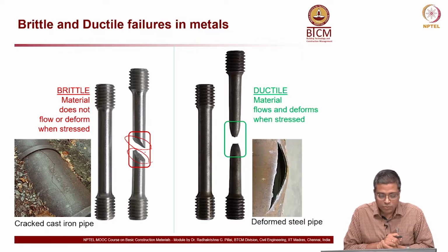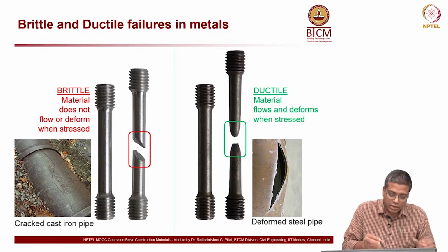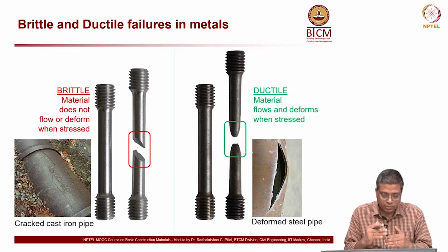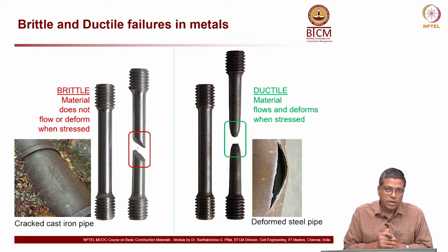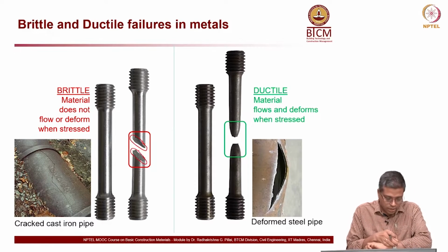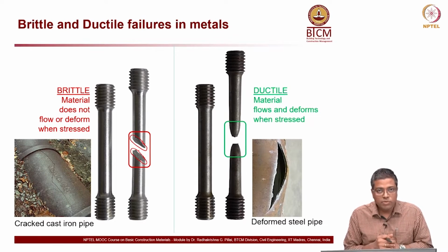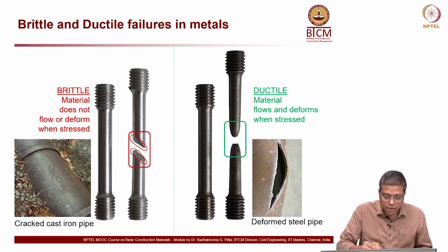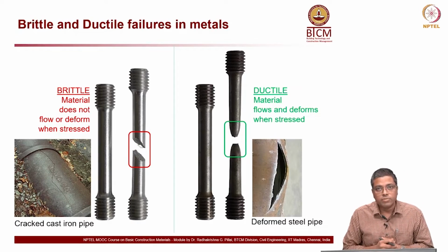There is no deformation at those fracture surfaces. In other words, the material did not flow much before it fractured. That means it is a brittle failure.